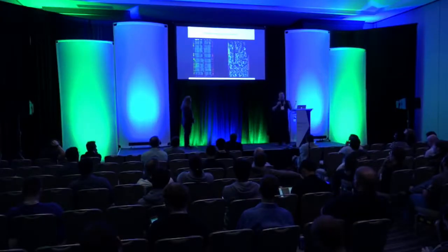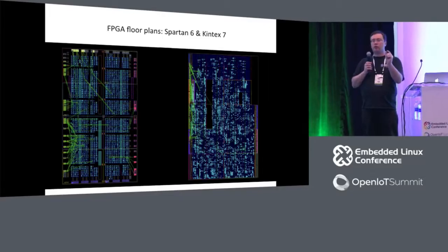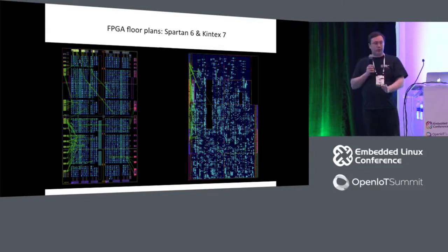Let me give a little more context for that. When we're talking about the DDR controller, most of these FPGA development boards come with a DDR controller chip on them that we're not using. The reason is, when you make an ASIC version of this, you won't have that. You want it all integrated on the SoC. Right. So we had to re-implement some of the things that these boards provide as little tiny ROMs around the edge of the chip, or as little tiny chips around the edge of the FPGA. You can get the size down by using the resources that are on the board, but that doesn't help you make your own actual chip.